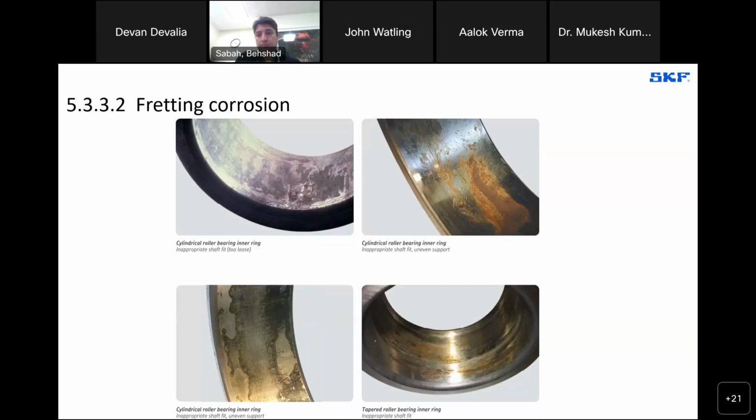And as I would say, when we're doing a bearing failure analysis, I'll be honest, it's not because of the quality. It's not a quality issue most of the time. Most of the time it is some deficiency in the facility, in the machine, like we said, largely lubrication related, contamination, etc. So our customers are coming to us, and I'll be honest, it's not only SKF bearings that are analyzed.